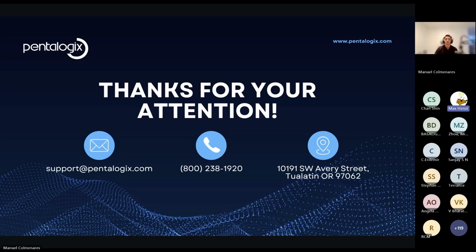Manuel briefly mentioned something about the PCB Navigator. This is a relatively new tool. It's something that I'm excited about. It adds intelligence to Gerber data, and it makes it a lot easier to navigate around your design. So we essentially import a bill of materials, we import a pick and place file along with your Gerber data, and now we can tie those three things together. Now you can, for example, say, show me U1, or go to R2, and it will jump to that component.